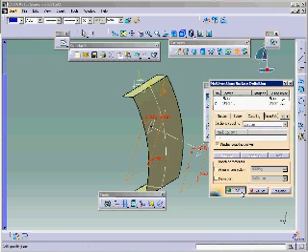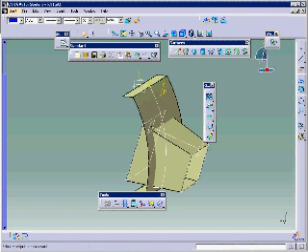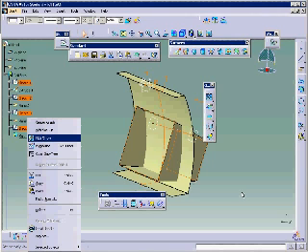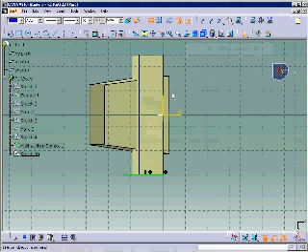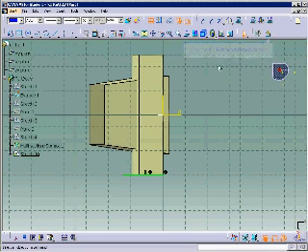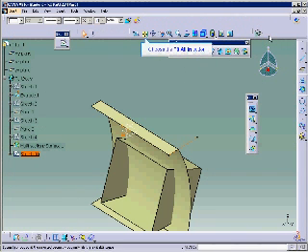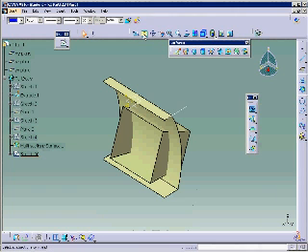Hide all the sketches and planes after the surface is generated. The model, after creating the multi-section surface, is displayed. Next, you need to create the surface on the right of the base surface. Select the top face of the base surface, and invoke the Sketcher workbench. Draw the sketch, and exit the Sketcher workbench. Extrude the newly drawn sketch using the Extrude Surface Definition dialog box by setting the value of the limit 1 spinner to 0 and the limit 2 spinner to 100.